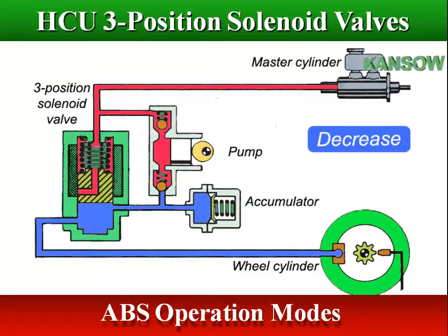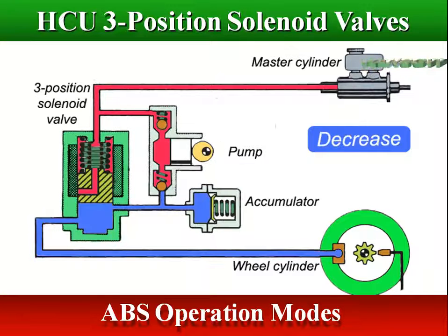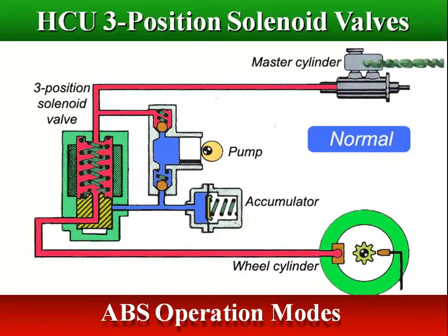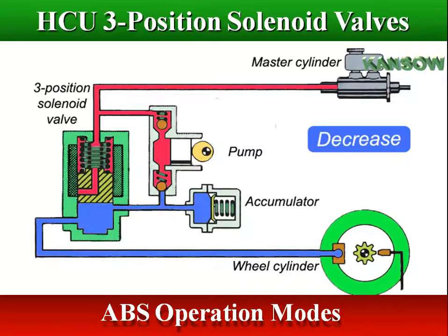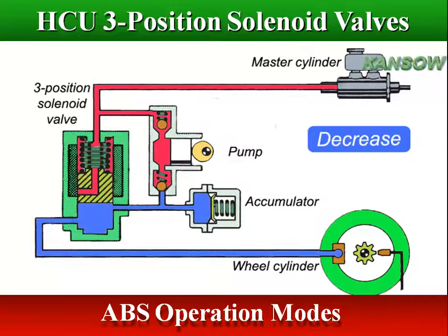It is normal in an ABS for the valves and the hydraulic control unit to keep changing position, as they change the brake pressure that's being applied. These changes in position may cause rapid pulsations to be felt through the brake pedal.